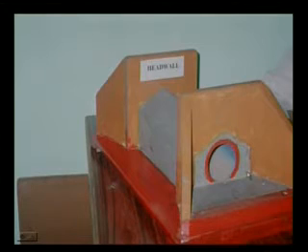Is it okay? In the previous slides I was also mentioning to you about the aprons. This is the apron on the downstream side. What does this apron do? It prevents the bed from getting eroded. This is a thick layer of stone masonry here. This is provided in order to safeguard the bed here from the gushing waters which are coming out of the mouth of the pipe culvert on the downstream side. A similar apron is also provided on the upstream side.